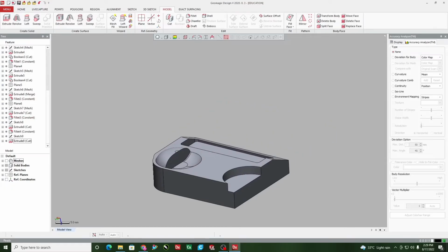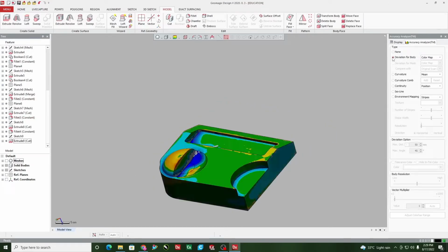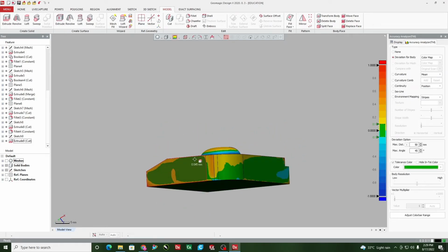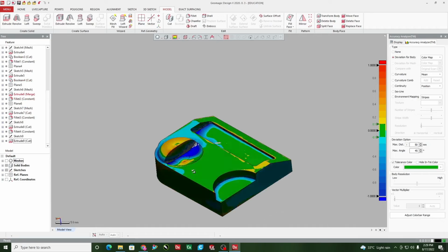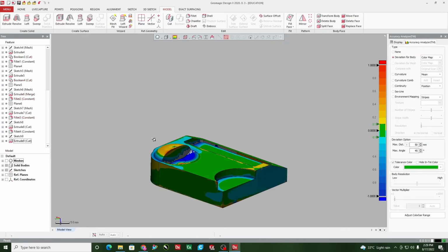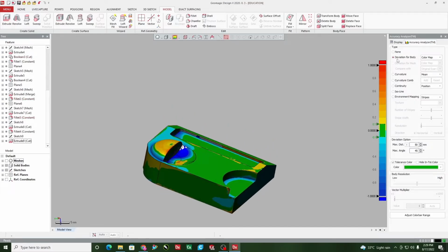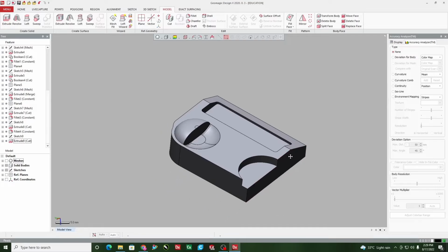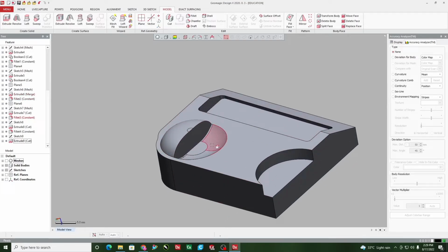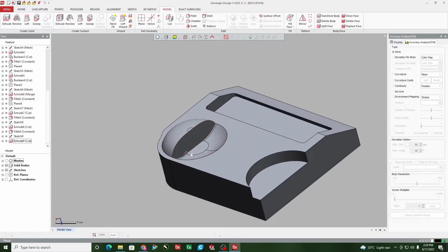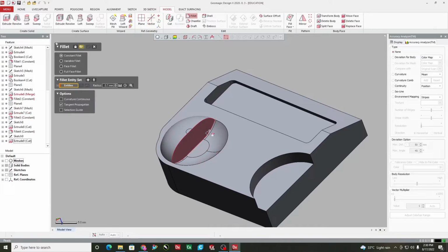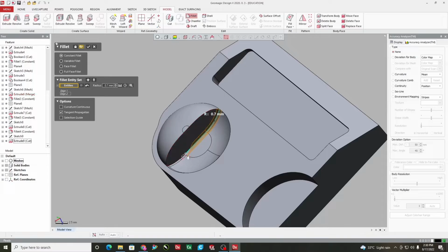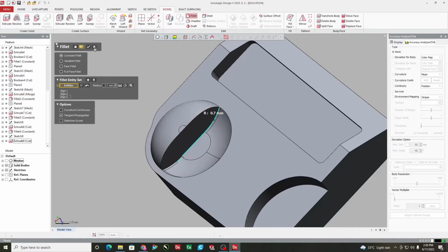Now, the solid body that we have generated is always checked through the accuracy analyzer. We just noticed that the dome circles were not matching because we thought of that as the exact diameter, but it was not the exact diameter when we actually see. You can see maximum of this is green, but still we are not able to get the perfect dome. Obviously, it is not a 1 hour or half an hour job. The operator has to work on it multiple times. Sometimes it has to do small manual cuts in the curvature, in the fillet, to make sure that using the accuracy analyzer we keep on obtaining the model that is closest to the mesh.